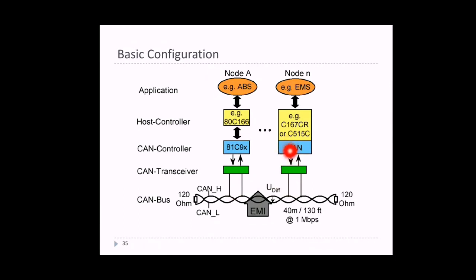After this you are also checking it with the CAN standards. Once it is satisfied, then you process it with your microcontroller. If you have any queries or doubts, you process and reply to me, then I can do the same process. So this is how the two nodes communicate. For this, communication should be secure, data loss should not happen, and there should be no EMI. So to configure these things, we have the 120 ohm resistance as well as the shielded pair. This is the concept behind transmission and reception of the CAN protocol.